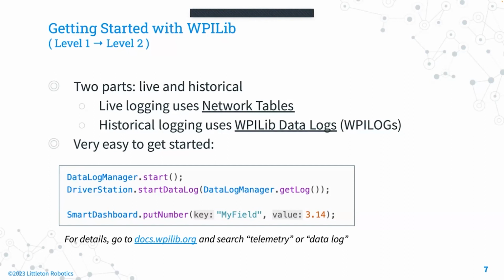The next line links the driver station class, which will log the robot status, whether it's enabled, and joystick data. The last line is just an example of publishing a field to NetworkTables, which will be both streamed live and saved to the historical log, the WPILog file.